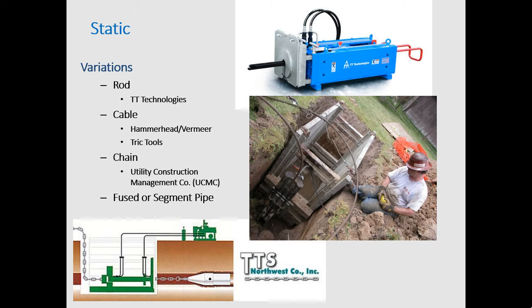They can use clay. Really what it does is as they pull it in, they have a clamp on the back that pulls that product pipe, that segmented pipe that's not continuous with it. Again, I can't really think of a really good reason why you'd want to use that. I think you'd rather just use a restrained joint pipe or continuous through your product or through your project.